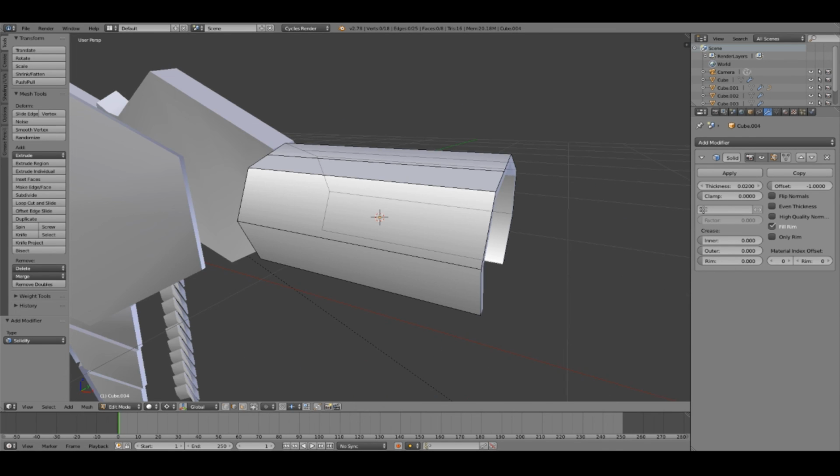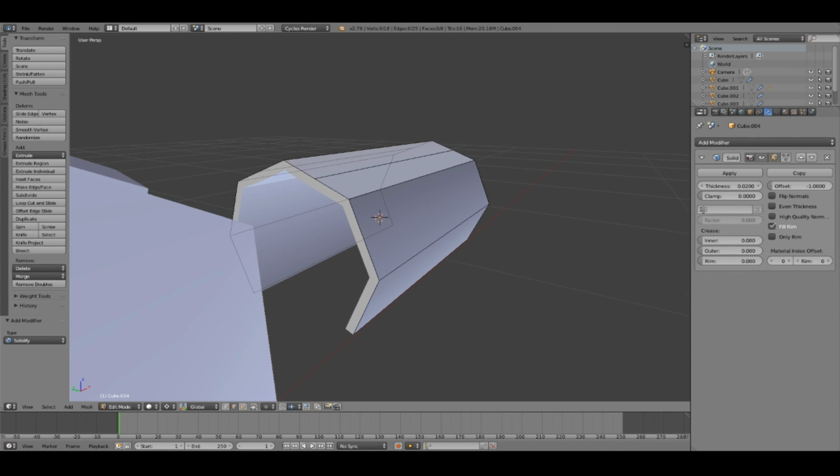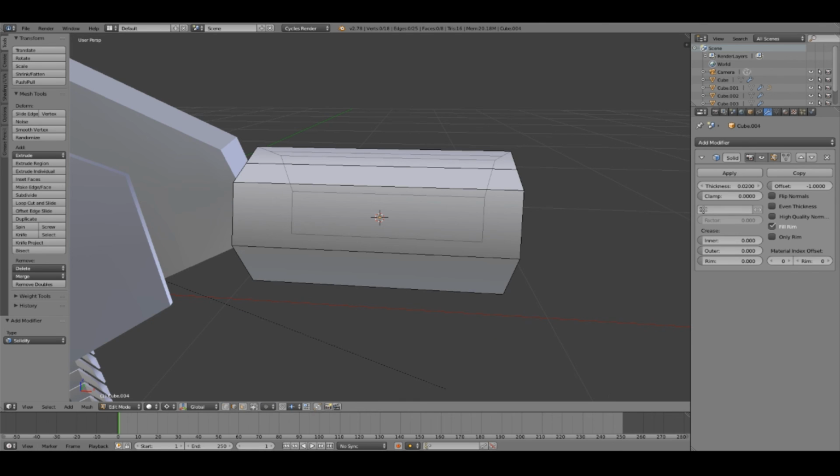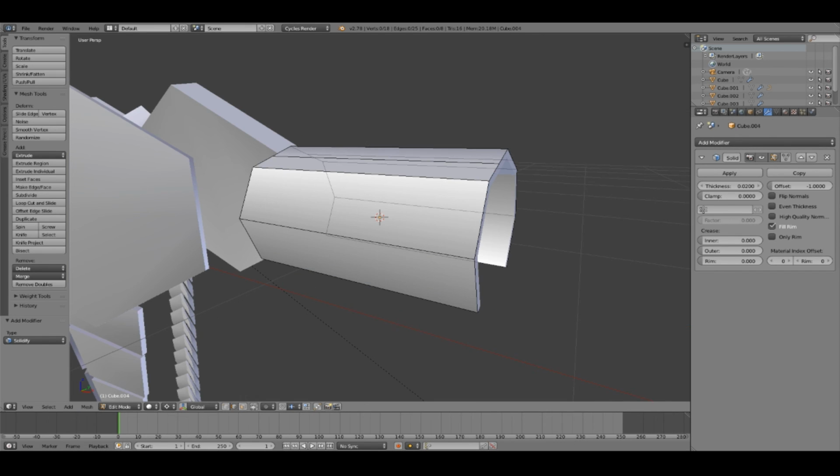And then we can add some beautiful little details later. Probably have a couple of edge loops across. I can't show you. Why can't I show you? Oh, because I hit F N R. I hope that didn't do anything stupid. Control R, and we're going to do about 3 loops, just to give you a perspective.